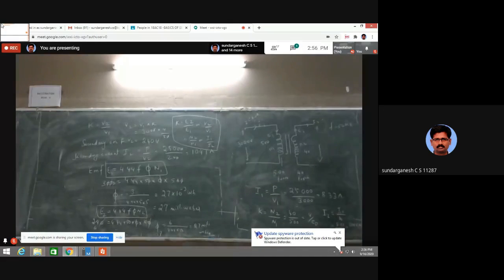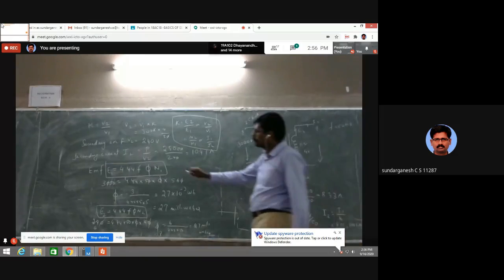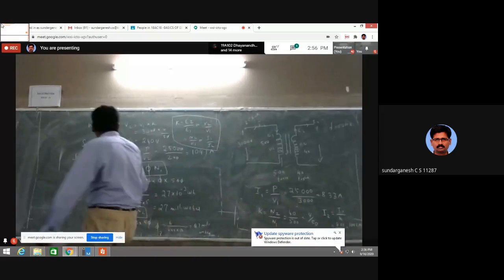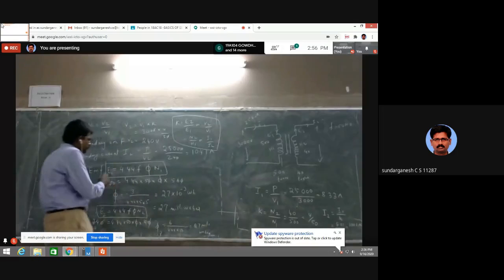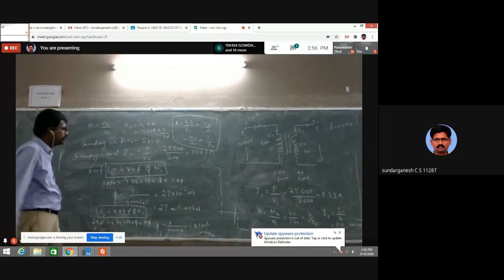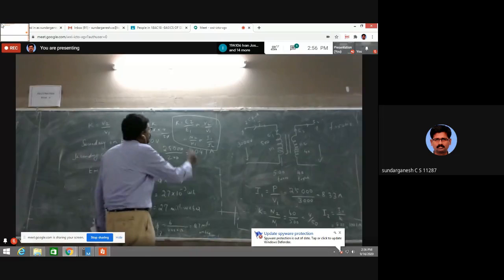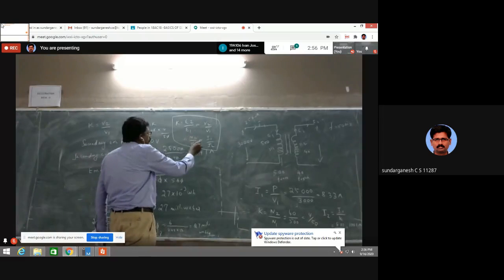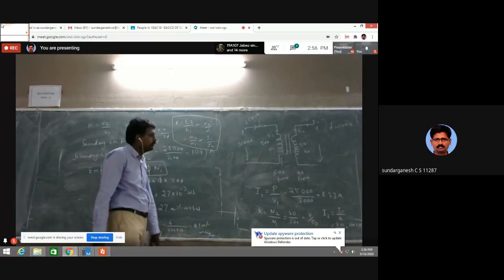So you have to know three formulas. P equal to VI, power equal to VI. Another formula, E equal to 4.44 F phi N. We use primary coil, it is E1 and N1. We use secondary coil, it is E2 and N2. K is equal to E2 by E1 or V2 by V1 or N2 by N1 or I1 by I2.